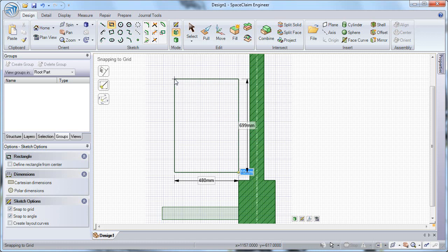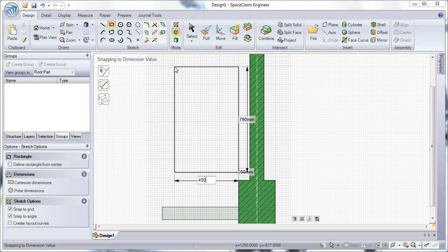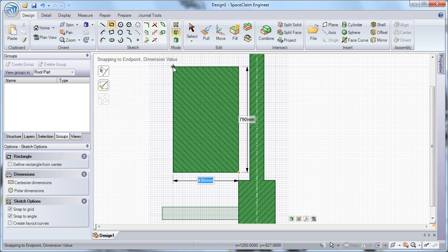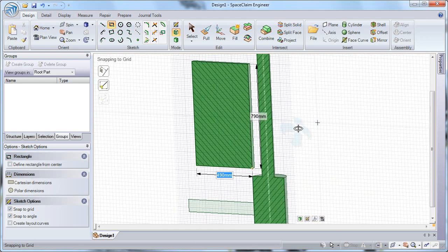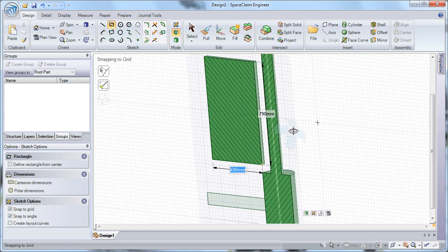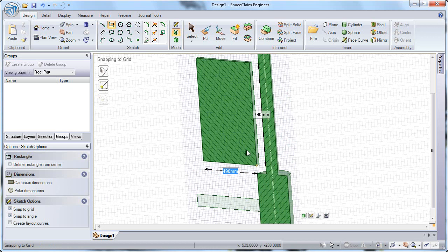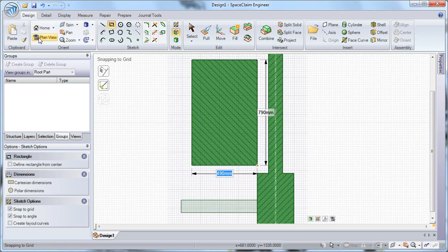I can change the other dimensions as well by tabbing between them, and when I've specified all 3 dimensions, I'll hit enter, and it'll create that rectangle. Because of the option that I had set earlier to auto extrude revolve sketches in section mode, I'm getting a depth when I sketch in section mode, but not for the rectangle that I created in sketch mode.